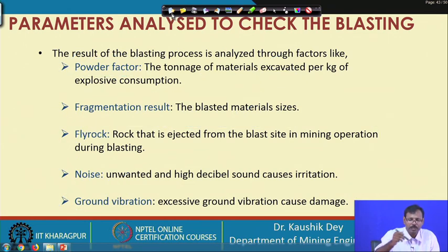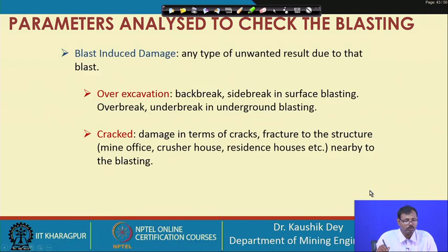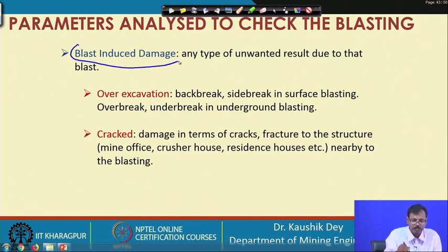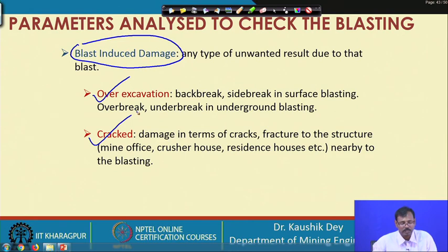So, basically these are the performance criteria one must consider while discussing the blasting process or evaluating the performance of a blast. So, let us start; a few more parameters are there. This is one very important, considering the effect on the remaining rock mass, that is how much damage has occurred to the remaining rock mass. One is called over excavation, another is the cracked formation in the remaining rock mass, that may result in the destabilization of the